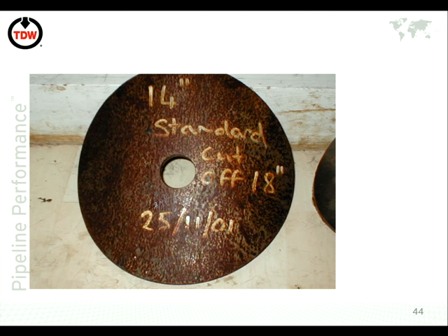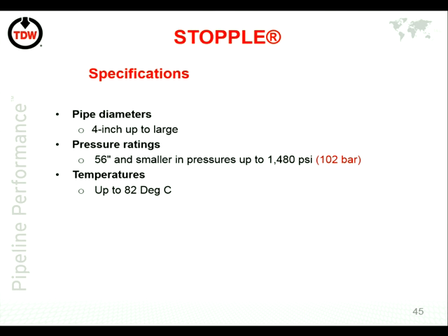Okay. Once you've got a hole in a pipeline, there's got to be a reason you've drilled that hole, for all of the reasons you're talking about. One of those reasons is that you would put a stopple in there, so you're actually isolating the pipeline for a period of time whilst you do something else. Stopples are just plugs which go in there and contain the pressure.